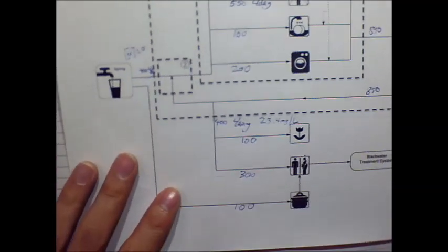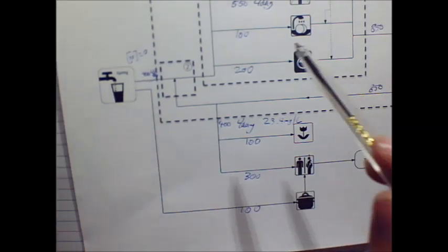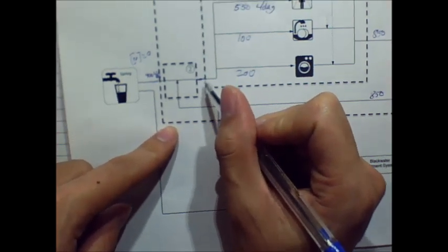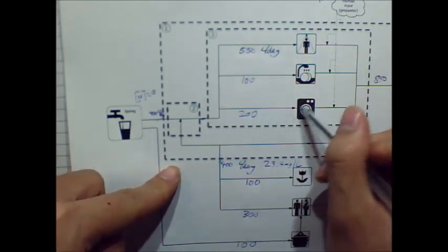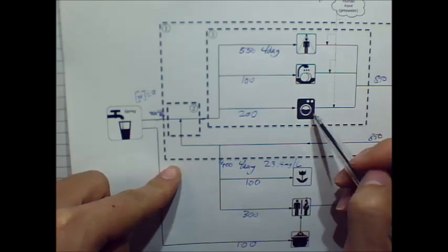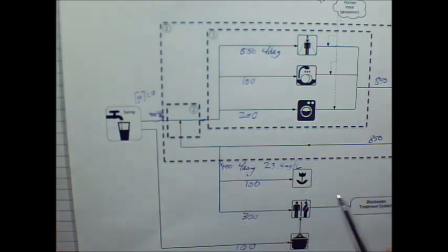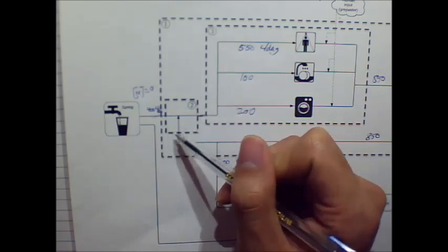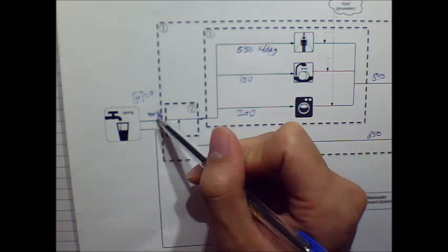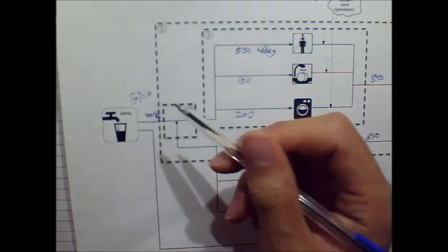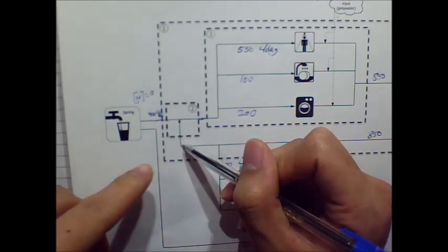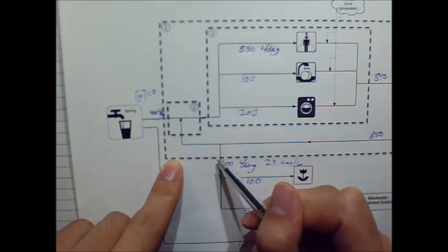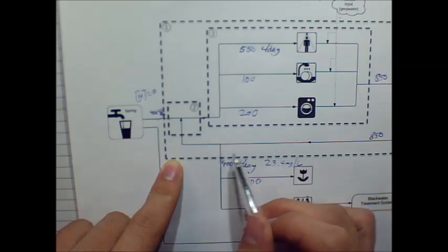Having a look at this, the question is asking what is the concentration of nitrogen coming in at this point here, because this point is what is going into the household. Remember, that's bathing, dishwashing and laundry. To do that, we can draw a boundary that crosses this line, and that's boundary 2. We're using this one because we have information about this stream already, which we worked out before. We also have information about this stream because we've worked it out down here. Remember, these two streams have similar concentrations because they're splitting off from the same parent stream.